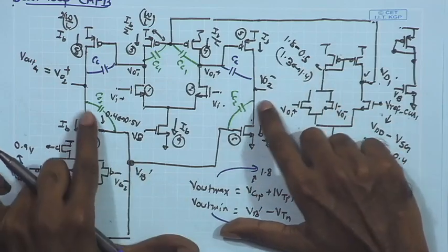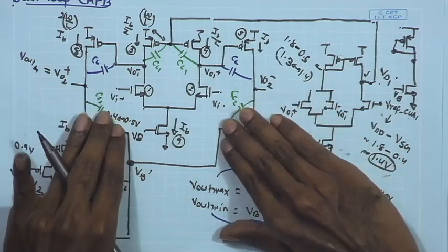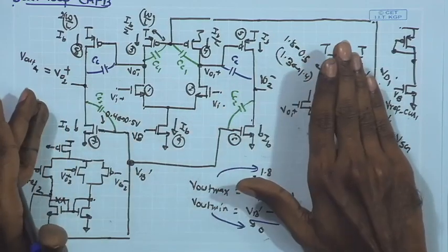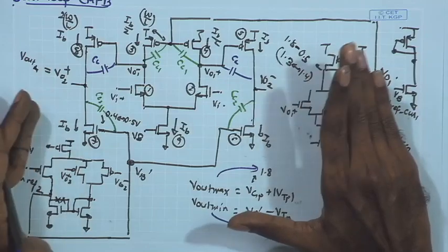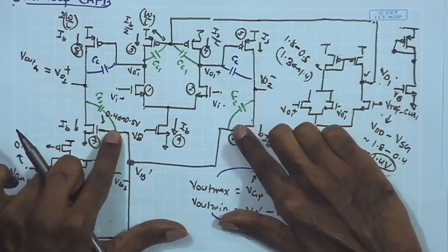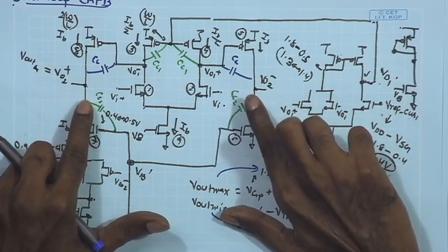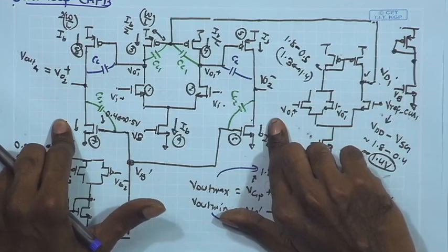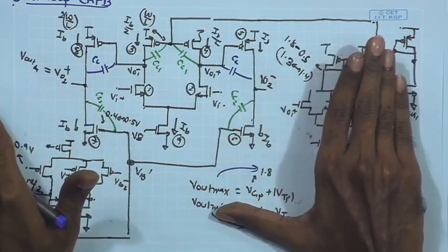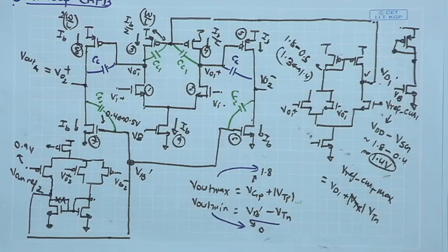As a result, the CC2 also appears as if it is between the output and AC ground. So, it basically can be clubbed with the load capacitance that you have for the differential operation, and as I said, the load capacitance can be significantly larger than the CC2 that you get. So, for the differential response, once again these CC2 are going to appear between the output point and AC ground as they are, without Miller multiplication, and they can be clubbed with the load capacitance. So, once again they are not interfering so much with the frequency response of the differential operation.